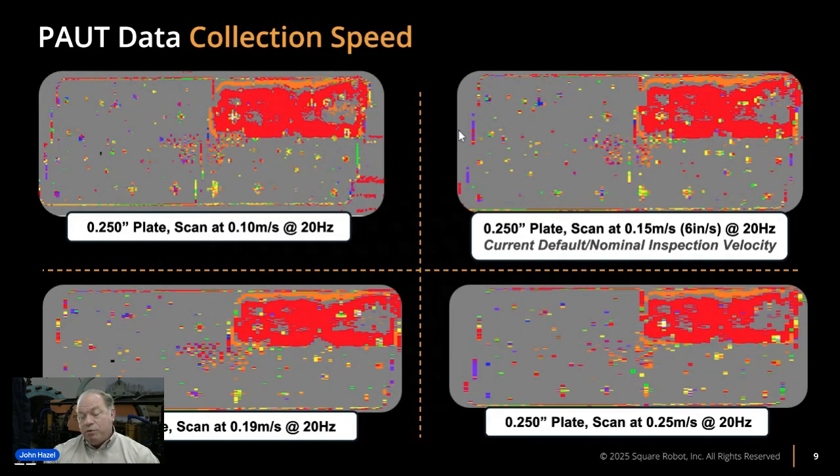From performing a lot of manual testing in my career, 6 inches per second sounds like an easy thing. It's really not that fast. And on a single element, that would be true. But when you have 256 of them, we're happy to have this data recorded so it's repeatable and we can look at all the data in our own time. And this produces quite a bit of data, collecting about 188 readings per square foot.